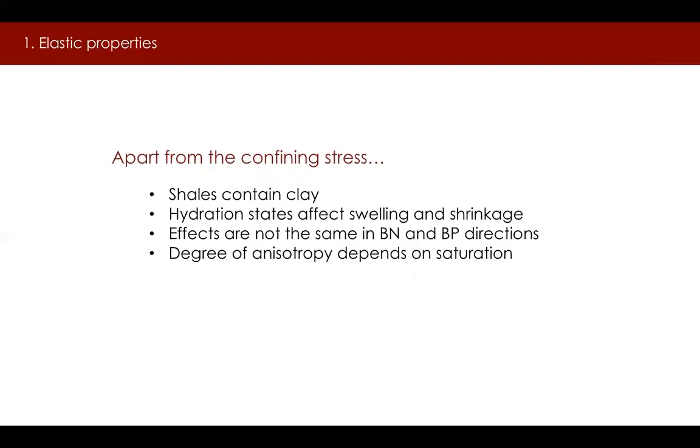Therefore, we can expect that the degree of anisotropy, which is the ratio between two elastic moduli, is not fixed, but evolves with degree of saturation. This is corroborated by lab tests on different types of shale.